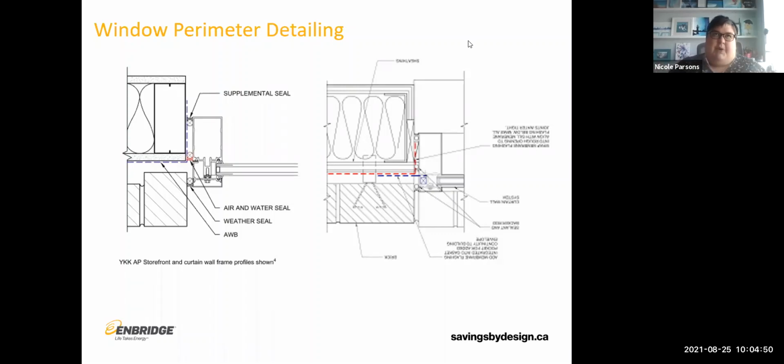And part of that issue is that there have been allowances in the building code in Ontario to ignore some of these things for a very long time. They've been trying to slowly roll out energy requirements and increase the requirements, and get the industry on board. So people have been allowed to ignore that in their energy modeling for their buildings, which is problematic, of course, because your building is not going to ignore it. You're not just going to not lose heat because you didn't model it, right?